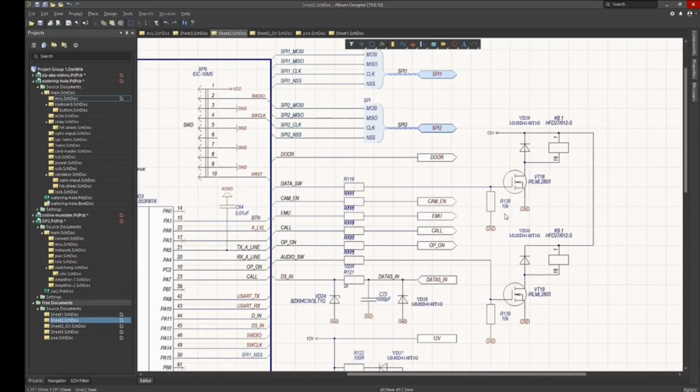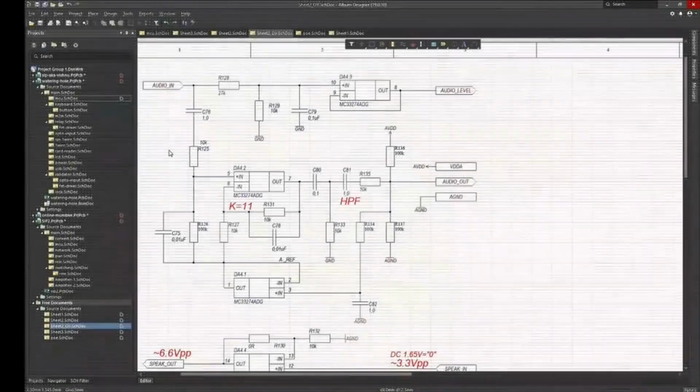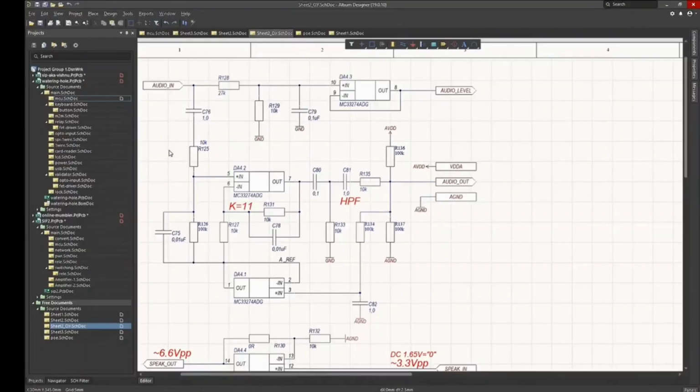Let's move on to the third mistake, not seeing typical stages. That is, almost any schematic consists of repeating blocks. Filters, amplifiers, a voltage divider, as in this case. Here is a voltage divider made of resistors. Here we have a non-inverting amplifier on an operational amplifier. Here we have a voltage follower on an operational amplifier. Here this RC network forms a filter. When you learn to recognize them instantly, any complex schematic becomes clear and predictable.